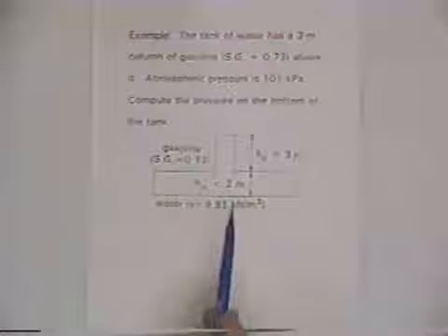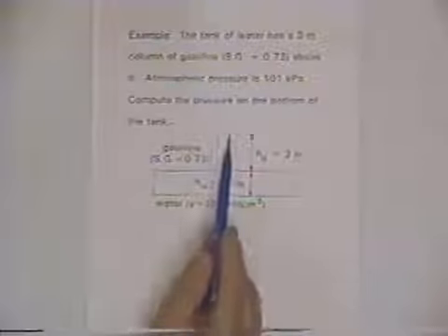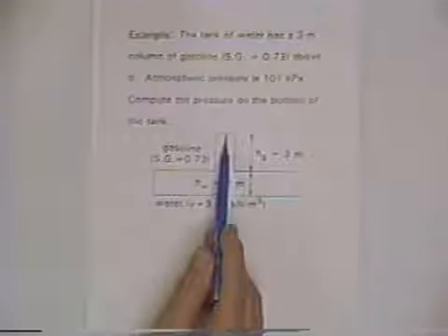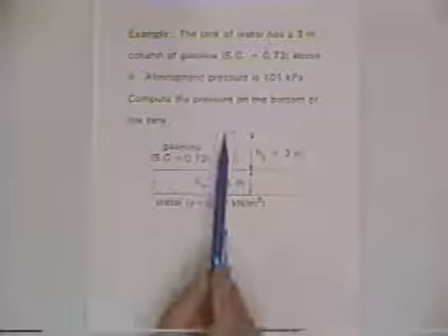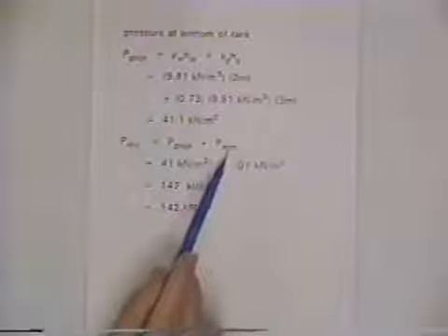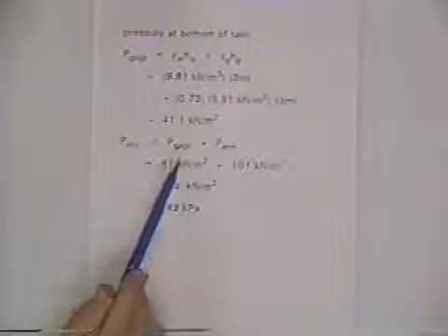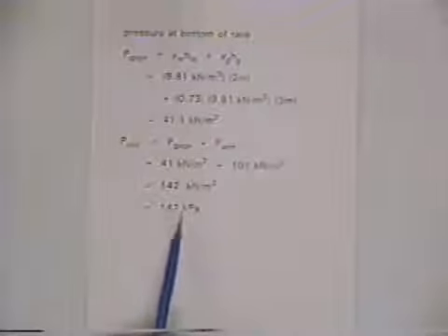per meter squared. And of course, if we go back to the diagram, the column of fluids above this point, we really left out one fluid because sitting above the surface of the gasoline, there's the atmosphere. So there's another fluid up there, the air. And so if we talk in terms of absolute pressure rather than gauge pressure, we'd want to add that column as well. And that's represented by atmospheric pressure. And so if we add the column of air, we'll add in the atmospheric pressure to the gauge pressure we just computed to get 142 kilopascals, and that's absolute.